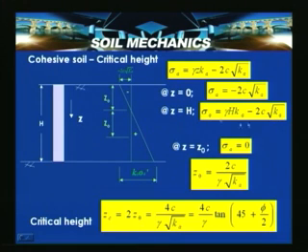So, which is nothing but earth pressure at the base. At z is equal to z naught, that is sigma A is equal to 0, that is this point here, then that z naught is nothing but the depth, that is 2c by gamma root over Ka. So, this particular depth is also referred to as the depth of the tension crack.